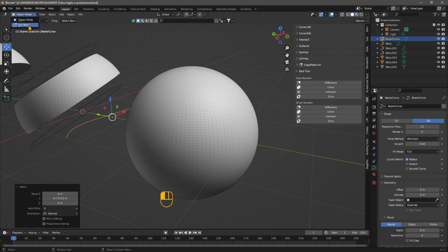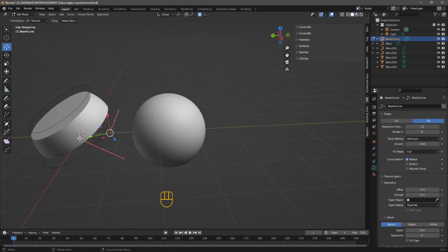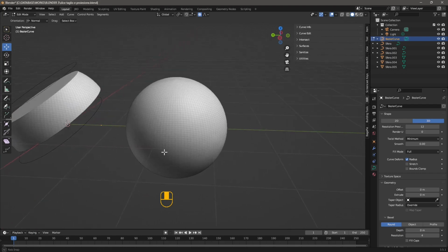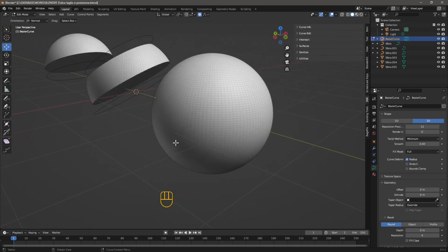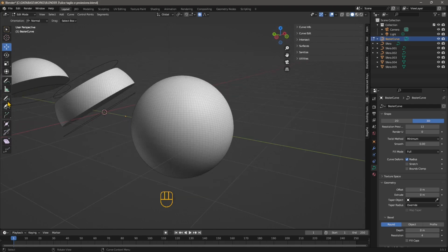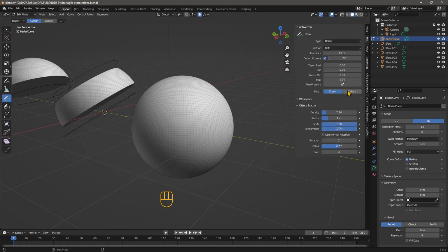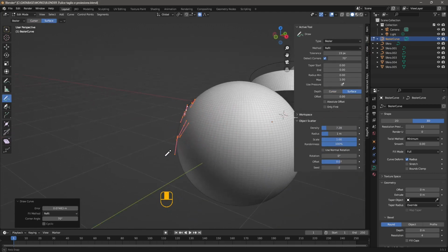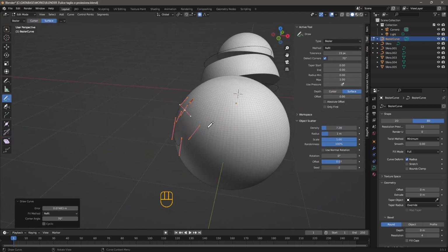And then if we go to edit mode, we can rapidly delete that because we don't really need that. So we just delete that and just delete vertices. It's fine. So we saw also in other video that you can do some sort of projection by using the draw mode and by going into the tool settings and use surface. This will draw on the surface. It's not going to be too much visible, but it's there.